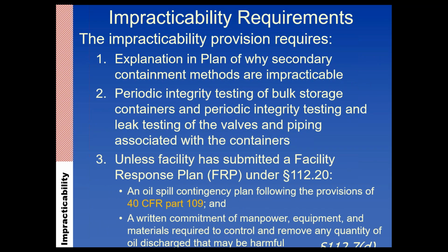What do you got to do if you do impracticability? Because remember, what you're doing is saying, I can't put in containment. Now, this applies for both the general containment and the size that we're talking about in a moment. What it says is, hey, I'm going to use a response plan. So basically, instead of containment, I'm going to respond to the spill. So not only do you have to have a plan, a 109 plan as we call it, and we have a copy of one in our guidance sample plan, but you have to be able to respond in a way that you're able to contain the oil and address any spills from your facility in lieu of having containment. But most importantly, you got to know when you had the spill. So impracticability has its place, but again, it has its disadvantages.